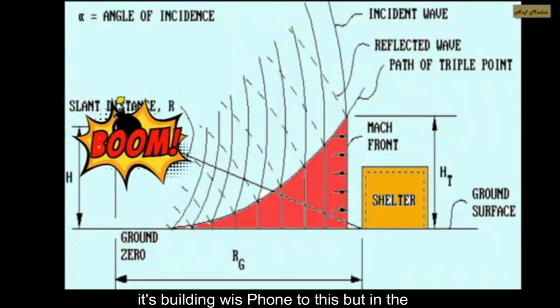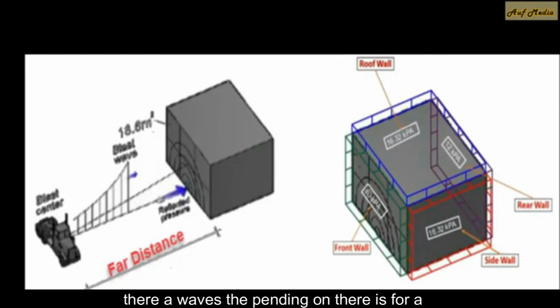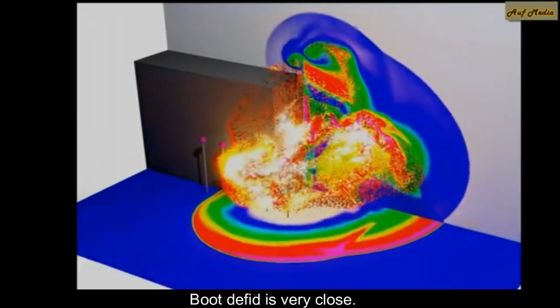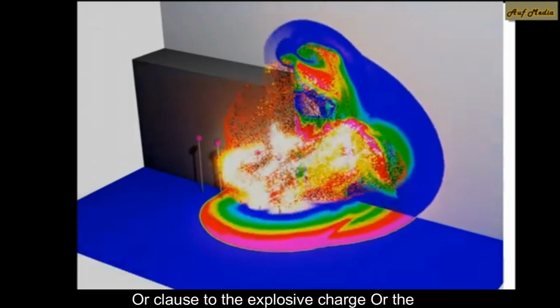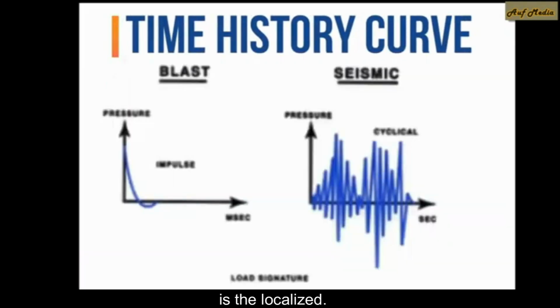In the case of the blast, there are waves too, depending on whether it's far or close to my building. If it is far from my building, the whole building will be affected globally, and it will have a full response. But if it is very close, it will only affect the solid part close to the explosive charge, so the only part affected is the localized response.